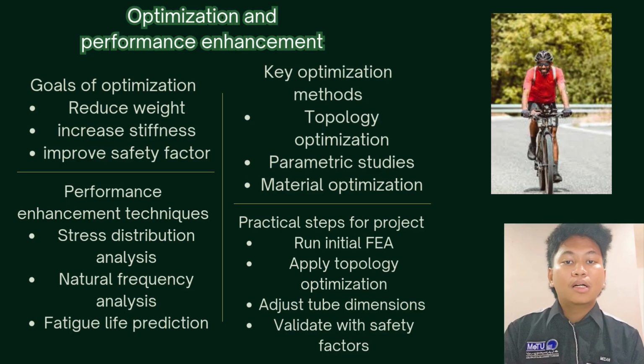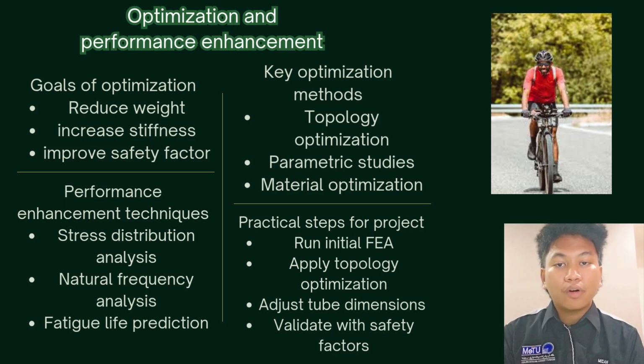Stress distribution analysis helps in identifying areas of high stress concentration and redistributing them for better load bearing. Natural frequency analysis is vital for understanding how the frame vibrates under different conditions, which impacts comfort and stability. And crucially, fatigue life prediction assesses how long the frame will last under repeated stress, ensuring long-term durability. So in practice, the steps for a project typically involve running an initial FEA.